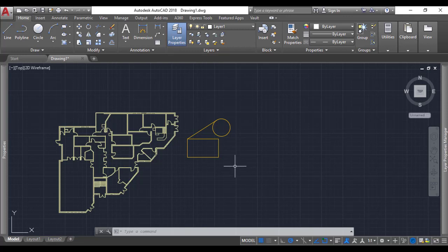Just some quick tips, other things that you guys can use is keyboard commands, which I've stated. Maybe go download some templates online or use the default templates that AutoCAD comes with. You can maybe go have a look at that and search on Google or search online for these templates. It also makes life easier. Maybe use external references. An external reference is something that you import within your drawing, such as a PDF document or an image or something along that line.